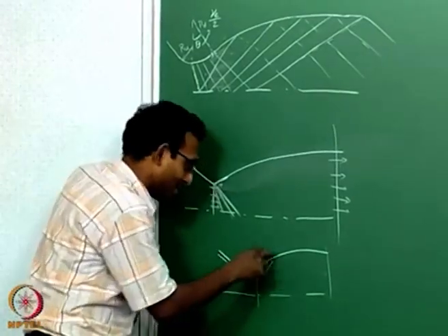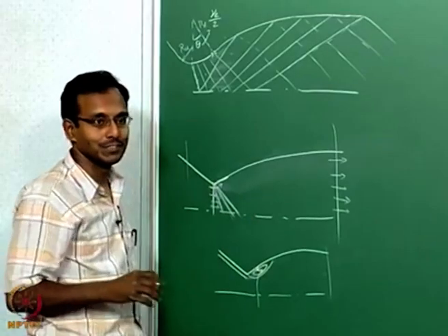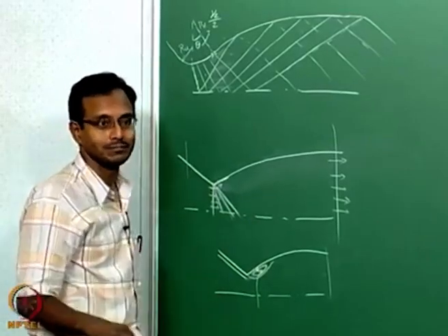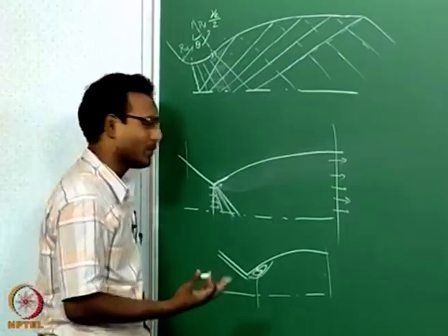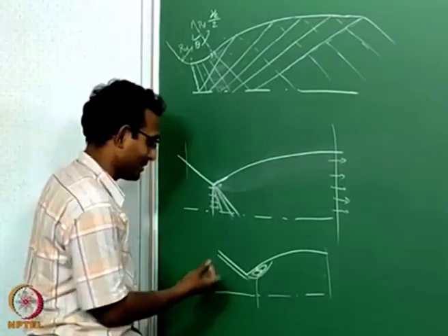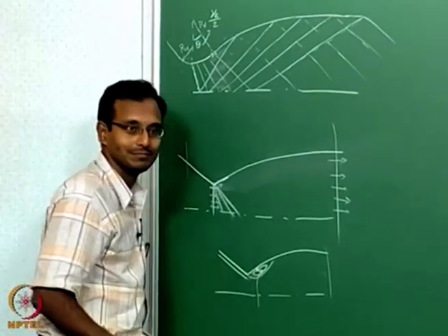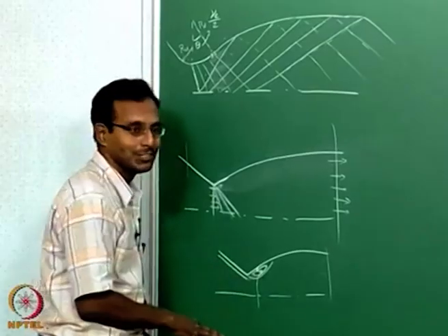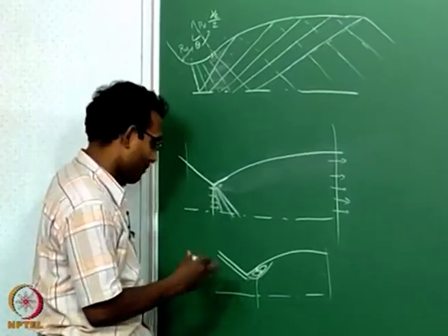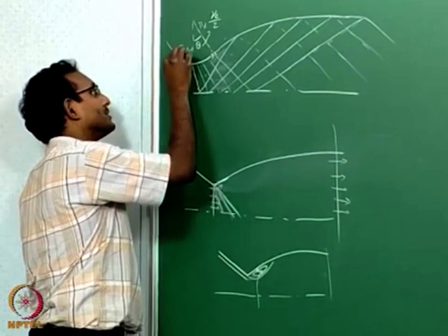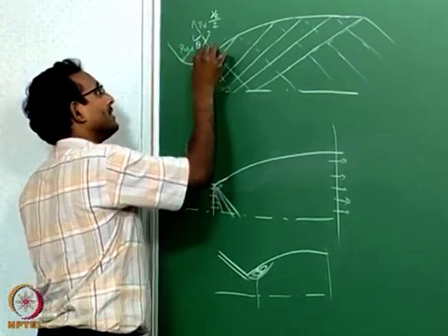You will never make a nozzle like this if you want to use it in a supersonic tunnel. You should never make this. It is better to use a straight line nozzle with a small curvature than this nozzle. This is the worst nozzle you can ever make, but a better one to make will be with this radius here and then another radius.